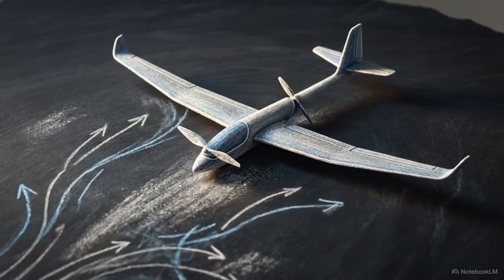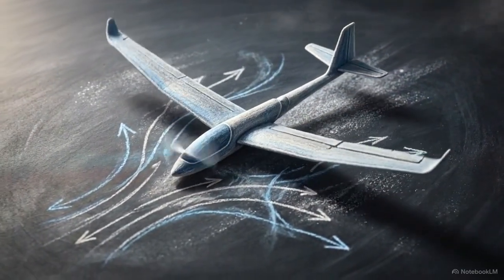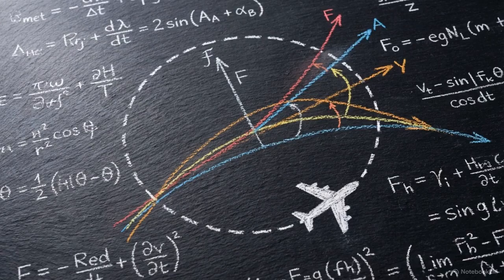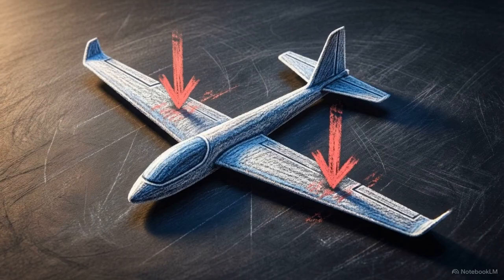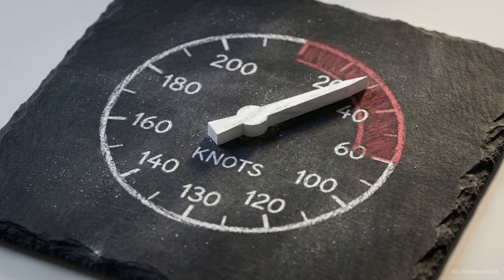Flying at this absolute minimum power setting introduces a critical mechanical danger. It forces the aircraft to operate precariously close to its stall speed, leaving almost zero margin for physical control. That danger compounds when we factor in the actual flight path. A loiter mission requires flying in continuous patterns. Banking the aircraft into a turn forces an increase in the aerodynamic load factor on the wings. Because stall speed scales directly with the square root of that load factor, any turn artificially raises the minimum speed required to keep the aircraft from falling out of the sky.